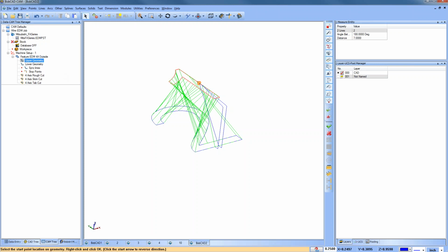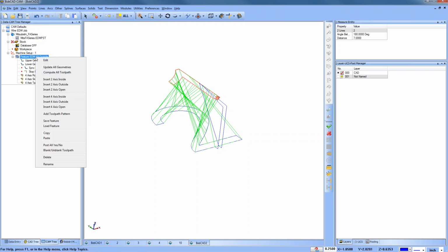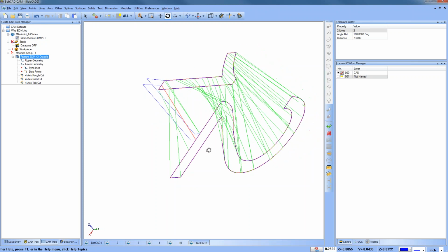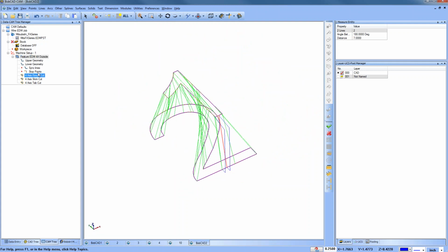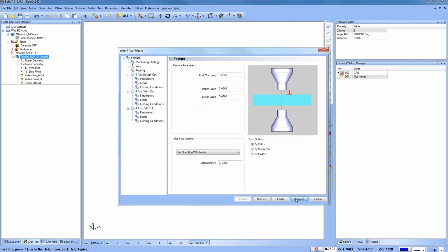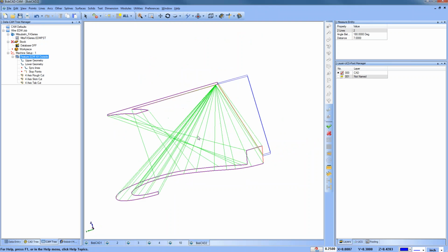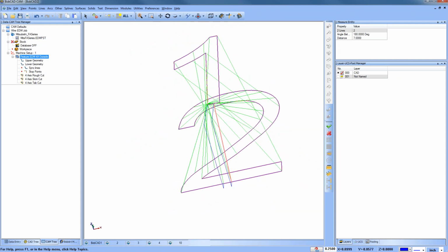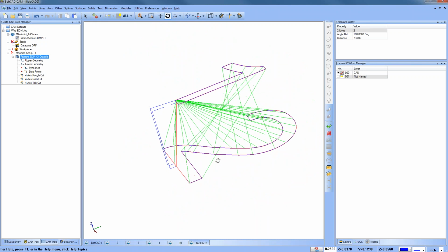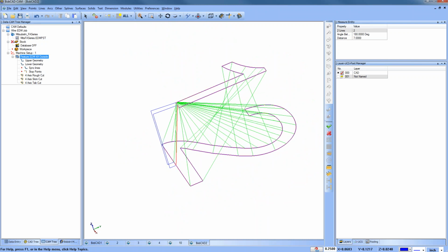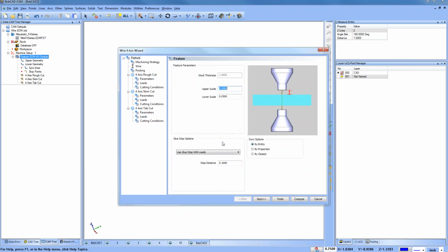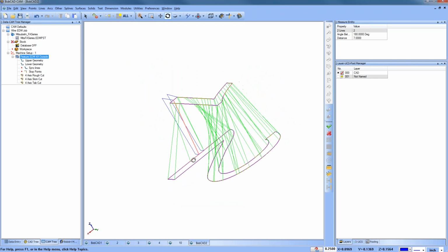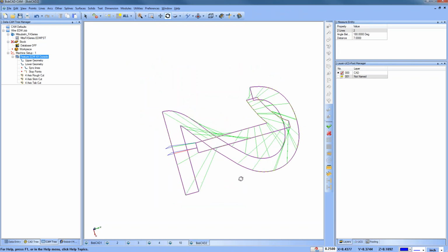So I'm going to move this start point over to here, hit my space bar to update it and recompute. Okay, so now that gives me this routine here. Now, it's really not the worst routine. If we look at some of our syncing options, if we go by entity, you can see that there are more shapes on the bottom than at the top. Generally what you've wanted in the past was an equal number of entities on the top and bottom. In the newer wire software here, you can do this by proportion. By proportion definitely cleans this up quite a bit in order to give us a more fluid path, okay?